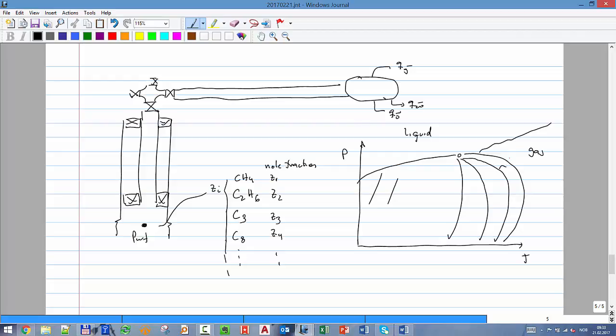Okay, that define how much vapor you have, that will be mass of gas divided by the total mass. Okay, this X, what I call the quality line. So here the quality is equal to 1, so that's the dew point line. That's when at that particular combination of pressure and temperature, I have exactly just the first mist of liquid condensing from the gas. This line is the bubble point line. That's where if I have a liquid, when I reach that particular pressure and temperature, I have just the first mini droplet, bubble of gas coming out of the oil.